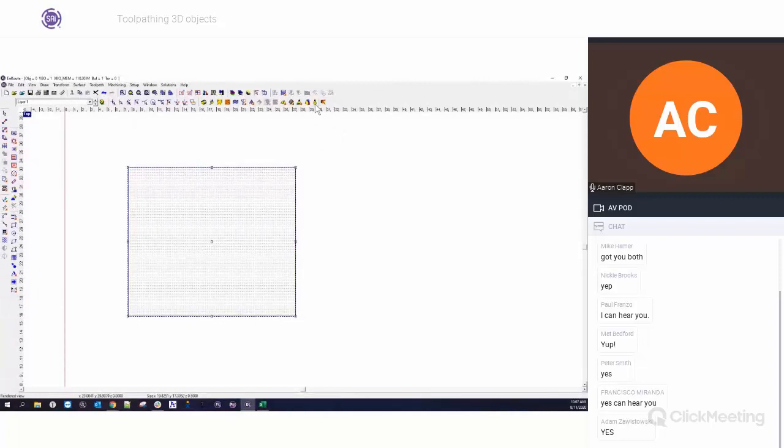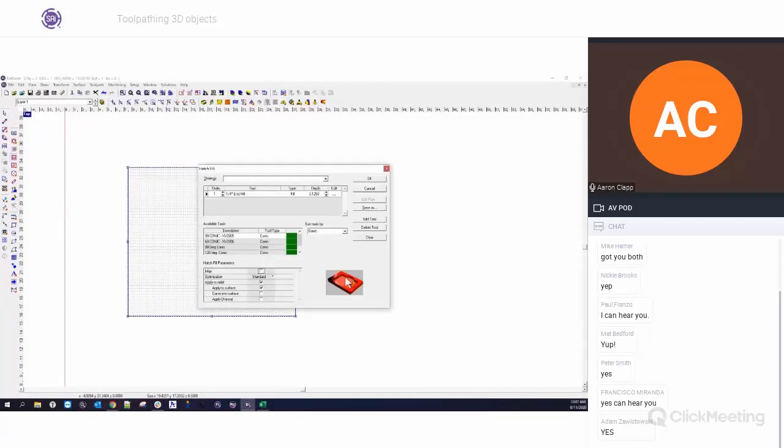One thing to remember is as we apply our tool pathing, so we'll go with our hatch fill, we're going to clear everything out. We want to use a ball end mill for most of these objects. There are some cases where you can use a conic tool, if the shape of your slope is exactly the same slope or same angle as your conic tool.